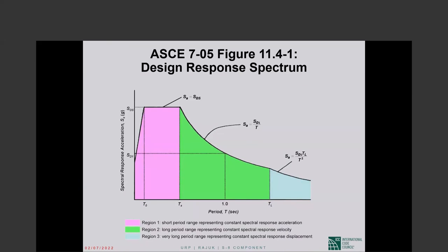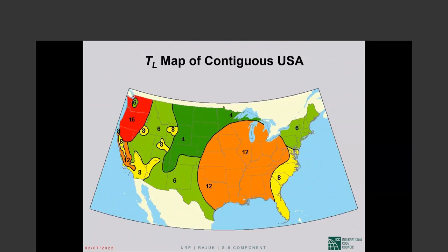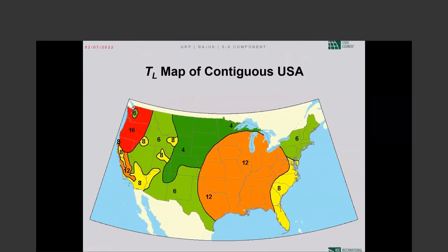Nothing is changed except that we now know that it corresponds to the design earthquake of ASCE 7, and the design earthquake is 2/3 of the maximum considered earthquake, which I have defined for you. Okay, so the T sub L.